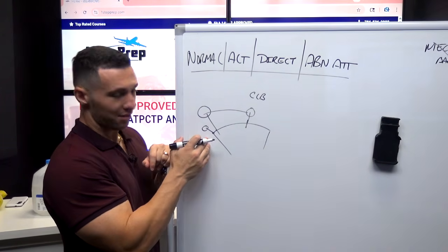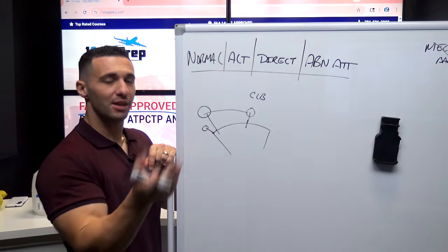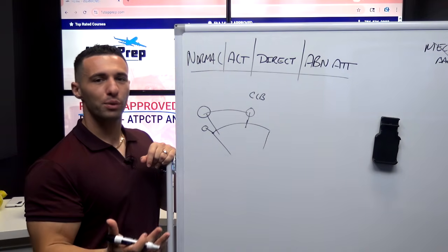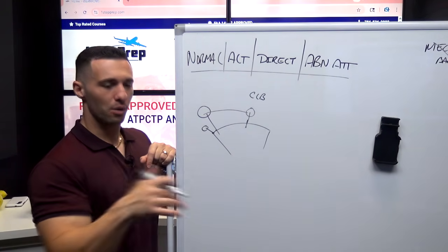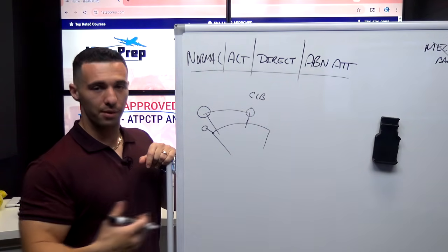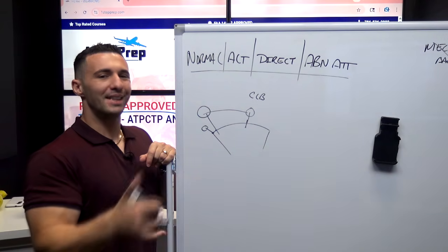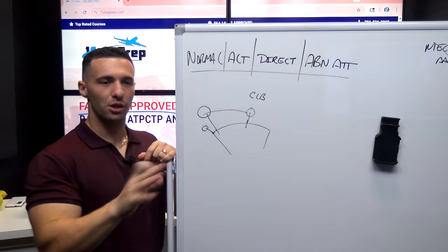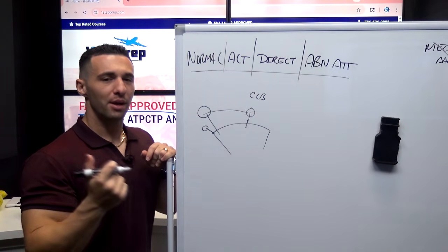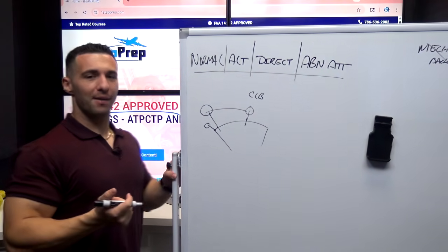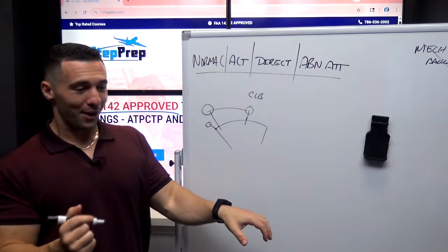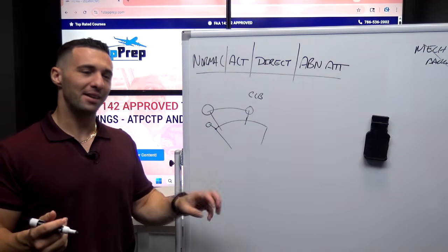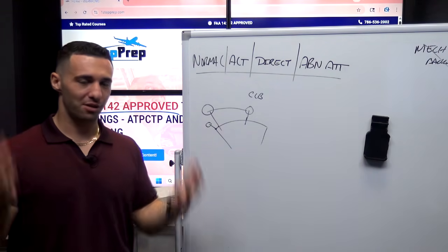Now, this would technically disconnect the autothrust. In fact, this is how we disconnect the autothrust all the time when we land. When the airplane says retard, retard, we grab the thrust levers and retard them all the way back to idle. We don't really disconnect the autothrust, unless you've been hand flying with no autothrust from way back on final. But on landing, it's not like I have to flare and then idle and disconnect the autothrust at the same time, which is what we do in the Boeing, by the way. We have to disconnect it manually because reducing it to idle doesn't do anything for us, right?